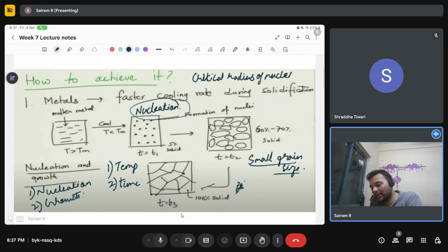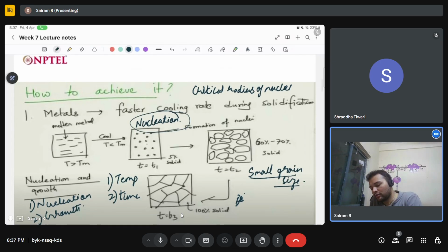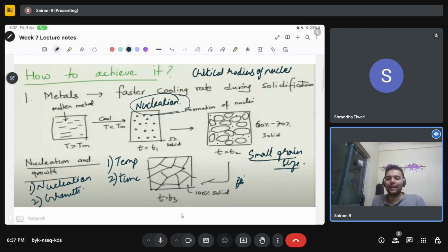So we not only have existing nuclei growing, but we also have other smaller nuclei forming, right? And it is always a balance. The entire process of nucleation and growth is a balance between time and temperature. The formation of these secondary nuclei is also very important, because these can help us in limiting the grain size, limiting grain growth, and a lot of other factors, right?